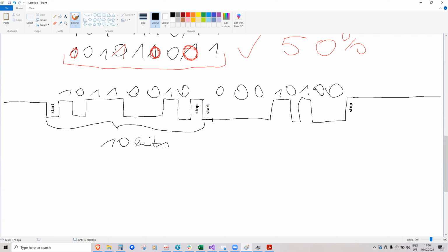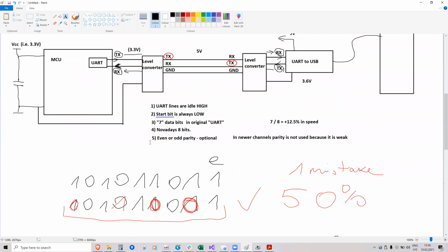But theoretically, some networks use 2 stop bits, so that when you send the bits, the 2 stop bits let the receiver kind of manage the byte before a new byte is thrown in. So 10 bits in this case, and the next transmission also has 10 bits, and with UART you only send byte by byte, so 10 bits. And this is why the speed in UART communication is expressed in bauds.